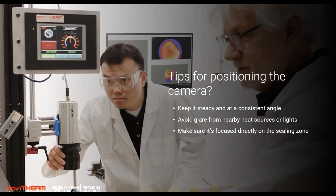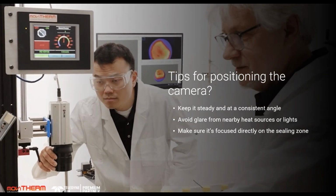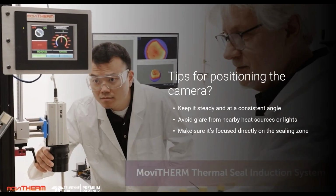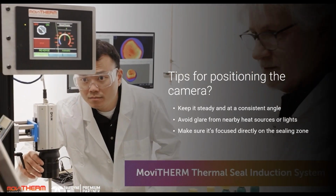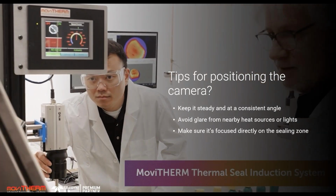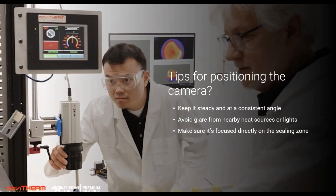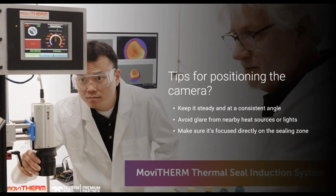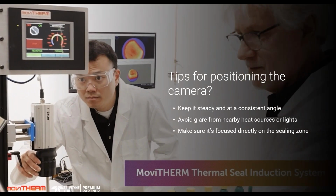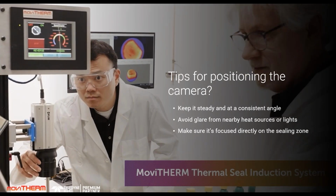Okay, yeah. Great. That's actually a really good breakdown of exactly what people need to consider when they're selecting the most appropriate thermal camera, and where they need to position everything to get set up for good results. It's basically completely vertically mounted right over the top. That's one of the key things here. You don't want to do it at an angle, so you do want to have that perpendicular to the cap.